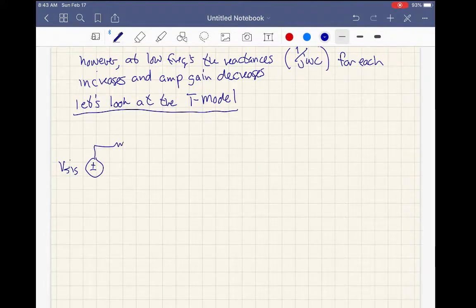Here's that source resistance, R sig. Here's CC1. Remember, our DC supplies end up looking like ground. So VDD becomes ground, and RG1 is shorted to ground.